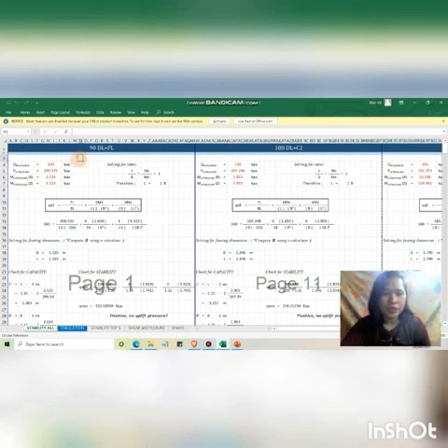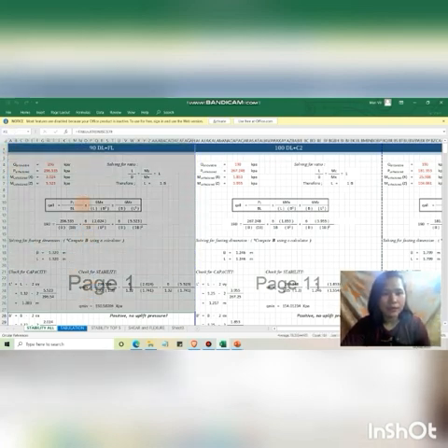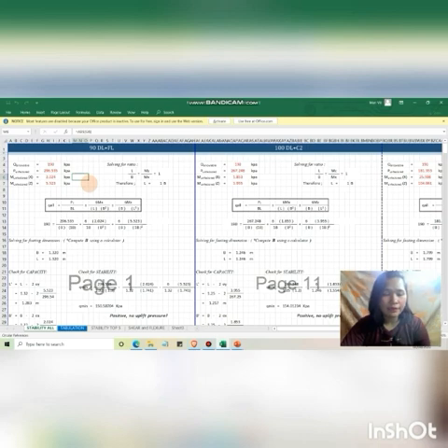For the other combinations, it is just the same as this load here. First, we will need our parameters. We need the Q allowable, or the allowable soil bearing capacity, the PY or P unfactored, the MX unfactored, and the MZ unfactored as our MY.